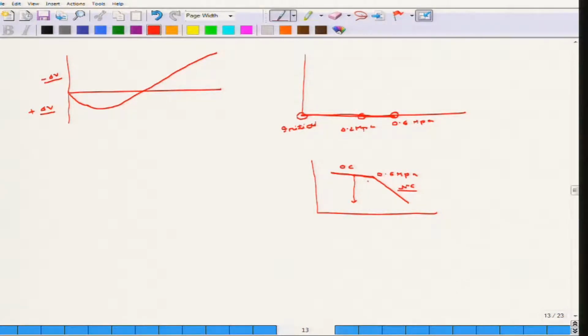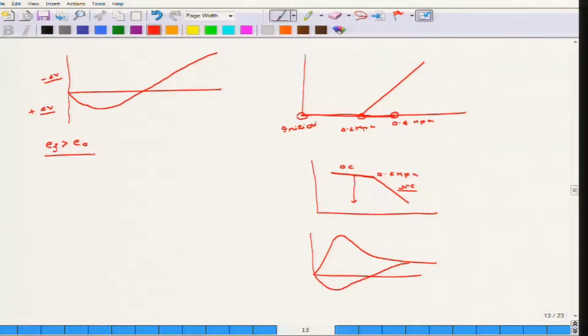So obviously it is in the over consolidated range, and since it is in the over consolidated range, you always know that an over consolidated clay will behave like this in case of stress, while the corresponding volume change will be equivalent to dilation. So since the corresponding volume change will be equivalent to dilation, obviously the volume is increasing. So the volume at failure will be greater than the volume at consolidation. While for the other sample, you know that e naught is constant.